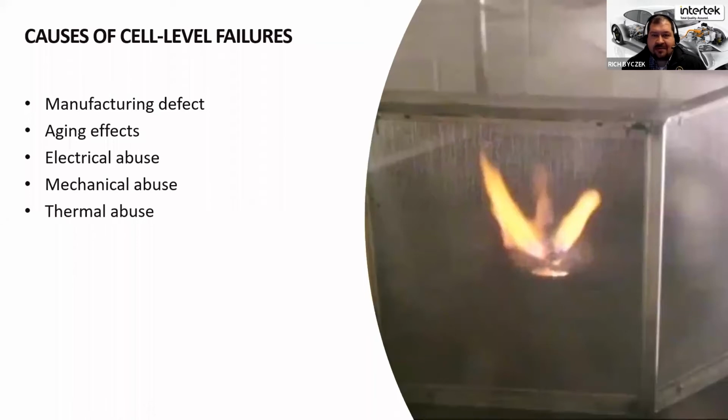When we talk about state of charge, that doesn't mean 100% and 0% of the physical capacity of the battery, but rather 0 to 100% of the usable capacity, where if it's discharged at 0%, you should be able to recharge it back to roughly 100%, and at 100%, you should be able to discharge it safely down to 0. So that's really an operational range of the battery, not necessarily the full capacity.